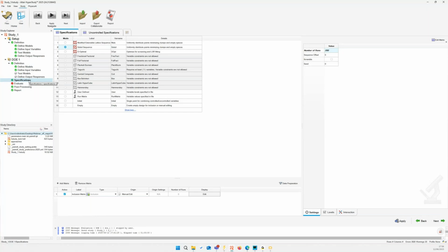Please take the slides and watch the tips I give and the common problems again and again, because these two slides I created come from actual client problems and may be helpful to you after this session. But you reach a steady state for all operating points, you get the efficiency, and then you can either have a 2D representation of this, or if you change other factors of the system, you will have a multidimensional efficiency map, which can then be deployed inside Activate as a PyFit or inside Simulink as an FMU in order for you to run complete drive cycles.